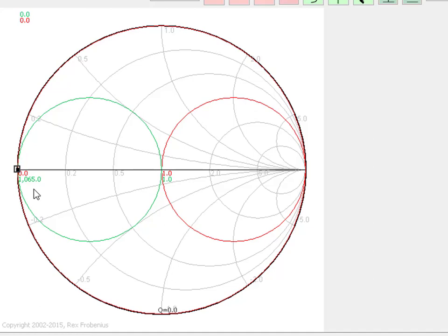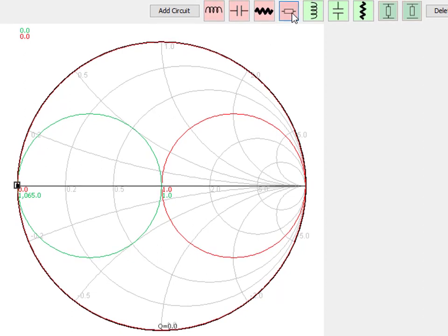You don't just have the output of the component tacked onto the ground. In the case of microelectronic circuits, you've got a via or some other trace between the component and ground. And then in other applications, you might actually have a physical length of line. And on the Smith chart, we can represent that by just adding a series transmission line, which we have available in the program here. Adding a transmission line ahead of the component has the effect of shifting the phase of the termination.